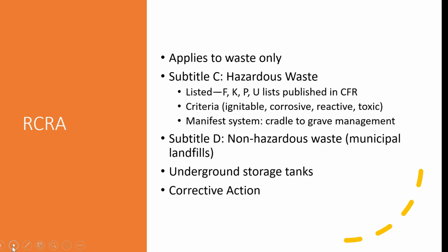So when you dispose of your trash, it is handled under subtitle D. And the most important thing that subtitle D did was specify the criteria for landfills, so that you didn't have town dumps anymore where people were just going and dumping things. That's what created Superfund sites. So subtitle D landfills are landfills that are supposed to meet criteria to prevent contamination of land and groundwater.